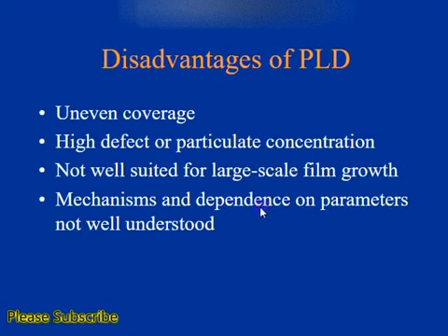However, there are a few disadvantages of the PLD process. The target material is exactly opposite to the substrate material, and that's why we can estimate that the surface that is exactly opposite to the plasma region will be covered with a higher number of atoms as compared to areas away from that point. That's why uneven coverage of the thin film is accomplished through this process, which is not desirable in most cases. And similarly, higher defect or particulate concentration is possible through this process,